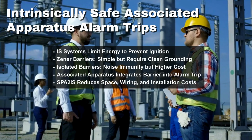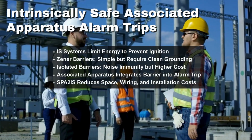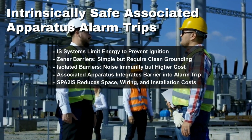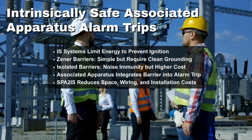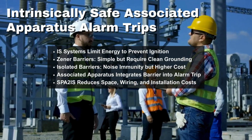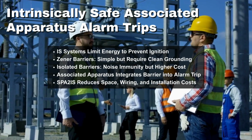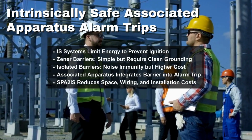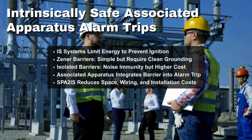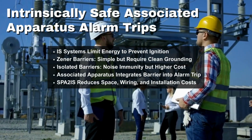In Part 6, we explored how intrinsically safe systems protect hazardous areas by limiting energy to safe levels. You learned how traditional IS designs require Zener or isolated barriers, and how each has trade-offs in grounding, noise immunity, and cost. We then introduced the SPA 2IS Intrinsically Safe Alarm Trip, which integrates the barrier directly into the alarm trip. This streamlined solution reduces wiring, cabinet space, and installation time, while keeping safety front and center.